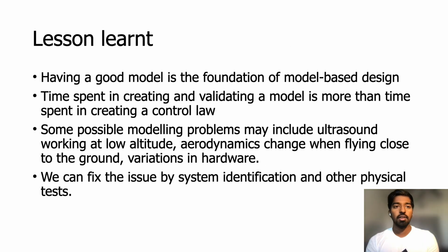Yeah, from this project, I have learned something important. To design a good model, we need model-based design. It serves as a good foundation here. And to create a good model, the time spent is more than to create an actual control law. There are some possible modeling problems, which may include the ultrasound because it may not work well at low altitudes, or aerodynamics changing when flying close to the ground, or some variations in the hardware. We can fix the issue by system identification and other physical tests.